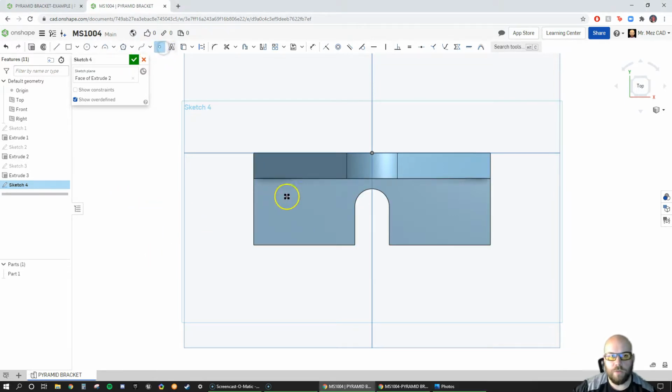Okay, so I'm going to come back over here. I'm going to pick that point tool. That's how they indicate where the holes are. I'm going to click, and I'm going to click, and then I'm going to put some constraints in. So these holes are horizontal from each other, on a horizontal plane across. The other thing that matters to me is where they are in relation to the center. So I'm going to go from here to here. That one's going to be 36. The other one's also 36 away, okay?